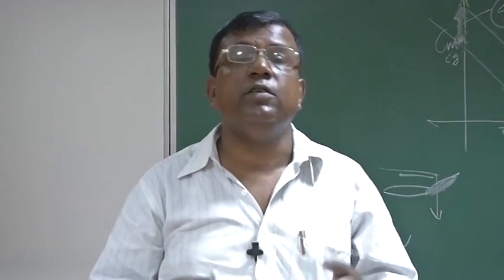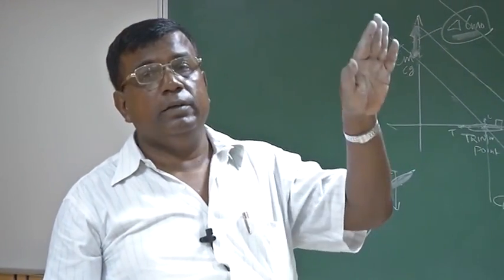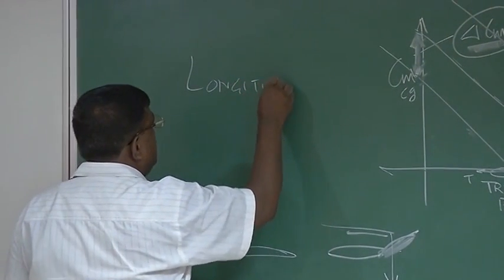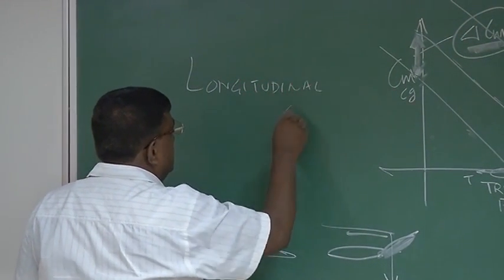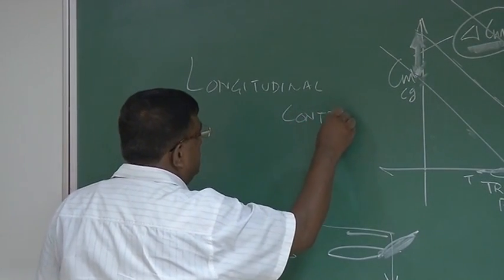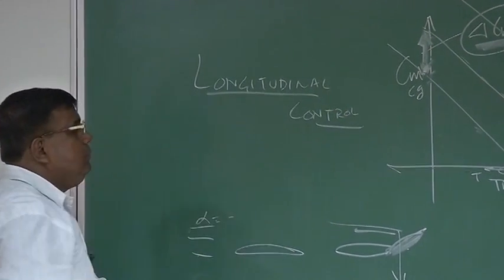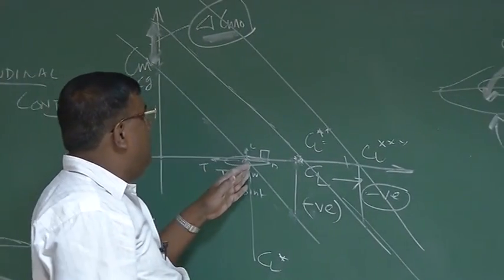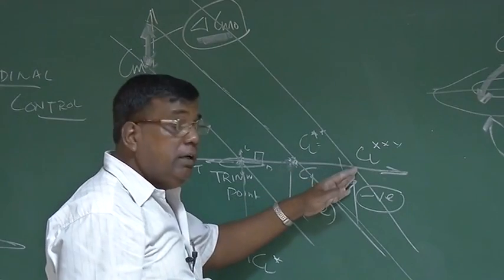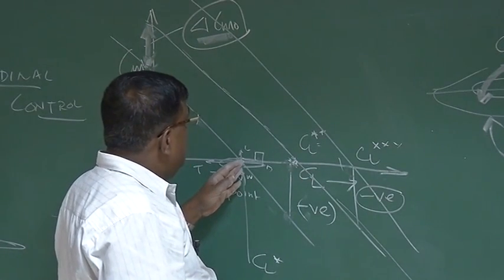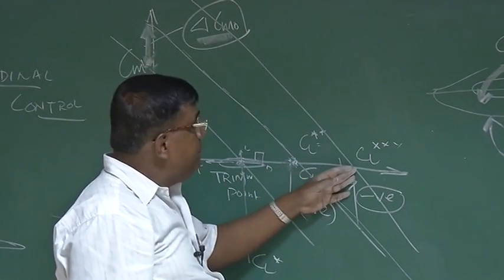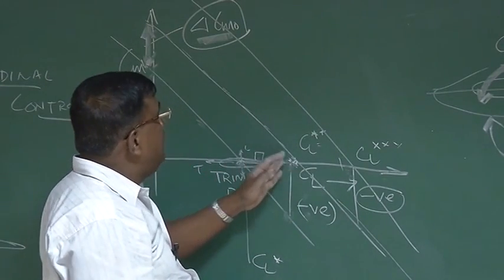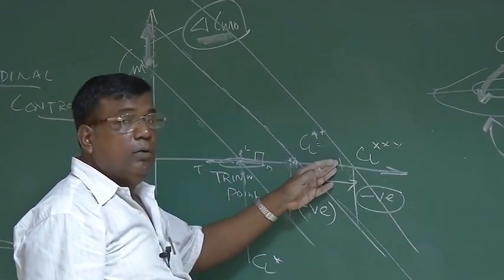One of the aspects of control of airplane in the pitch plane, or you call longitudinal control. This flying at different equilibrium, the different CL here, here, here, this problem we call control problem, and stability part you know here. So it gives you a connection between stability and control. Okay?